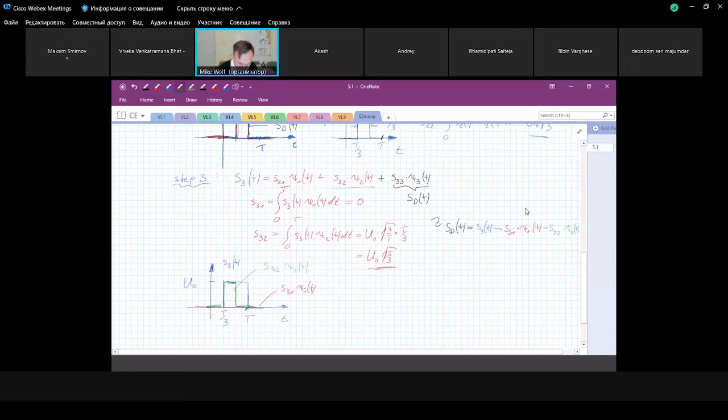And the difference, again, is our missed basis function. So we see, okay, here this is the difference, and this is SD of t. And of course, this is not complicated if we now want to map this signal into a basis function, we only need to ensure a unit energy. This means the shape is known. This is t. I draw it here. This is the shape, and now we normalize this corresponding to unit vectors in a traditional vector space.